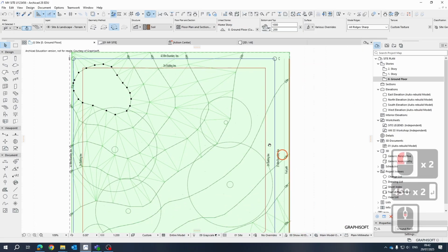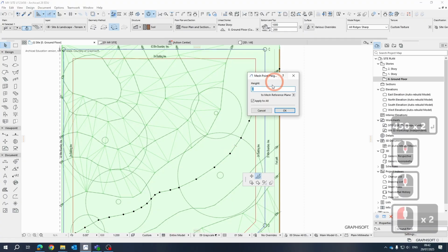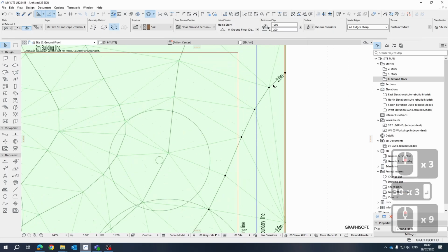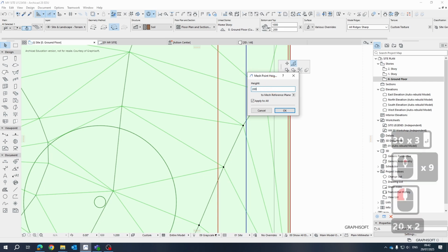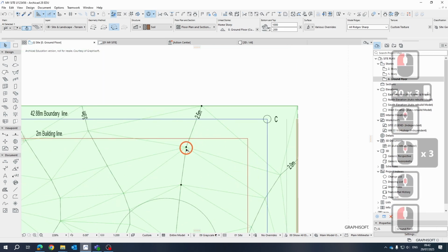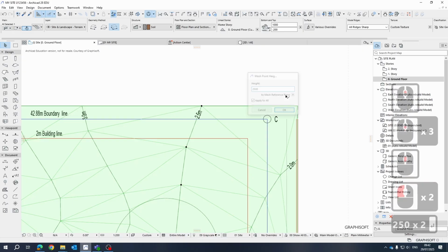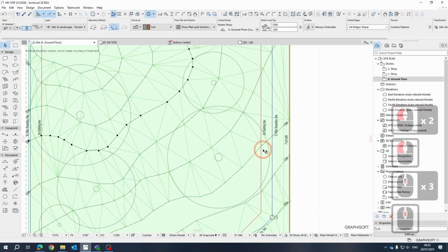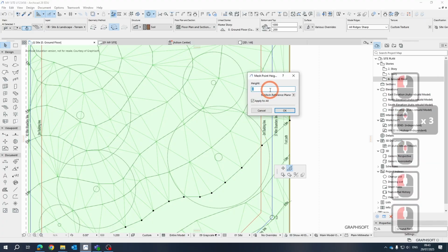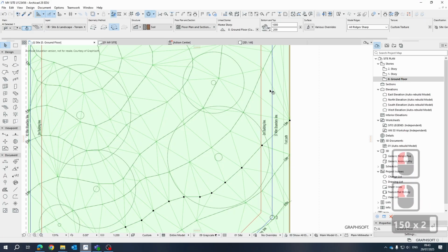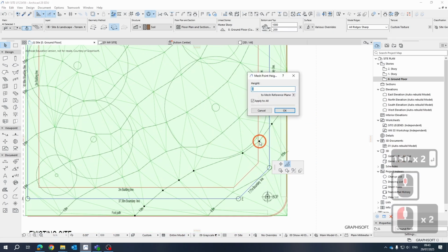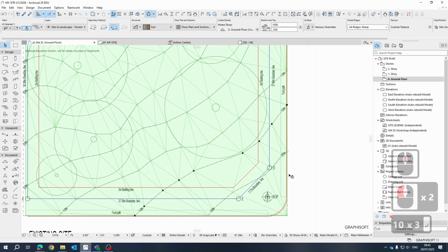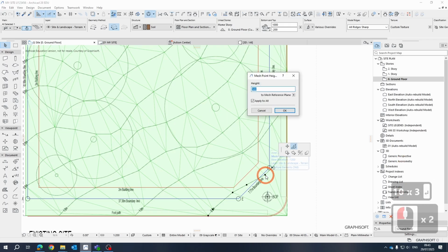Okay, so this will be 4,500, 4,500. So now you can see this triangulation that's happening on the topography. Okay, so that's important. So that must be 4,000. That must be 3,000, yeah, 3,000. At any point, if you're not sure, sorry, 2,000, you can go and edit these ridges at any point, so that should be 2,500. Good. So at any point, just go and double check, 3,000, good. And you can see the triangulation is starting to work now. So that is 1,500. Okay, and then this one should be a meter. Yep. And just make sure that that one is set to 500.